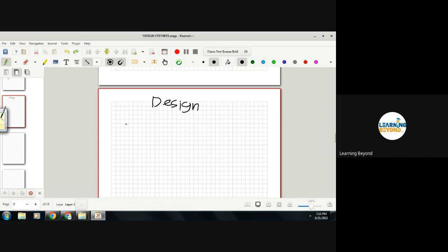So once we have a beam, what forces are there within the beam? Due to load, in the upper portion there is compression, and in the lower portion there is tension. Yes, so if this is the UDL, we get the bending moment. Let's assume this is simply supported for the time being. So there will be tension at the bottom and compression at the top, right?